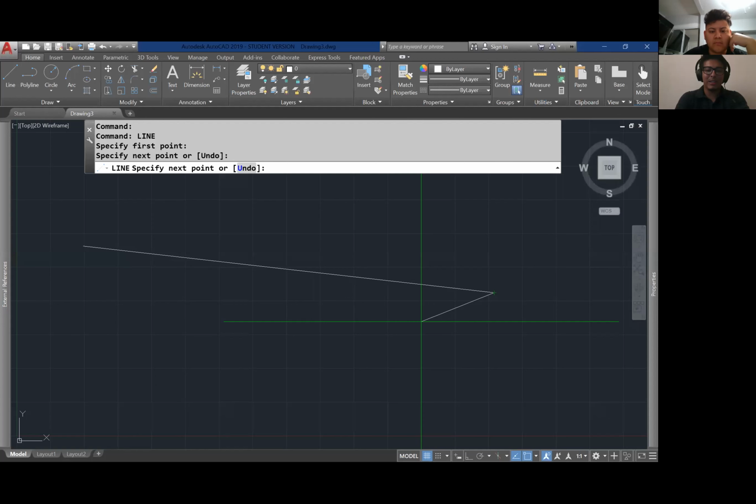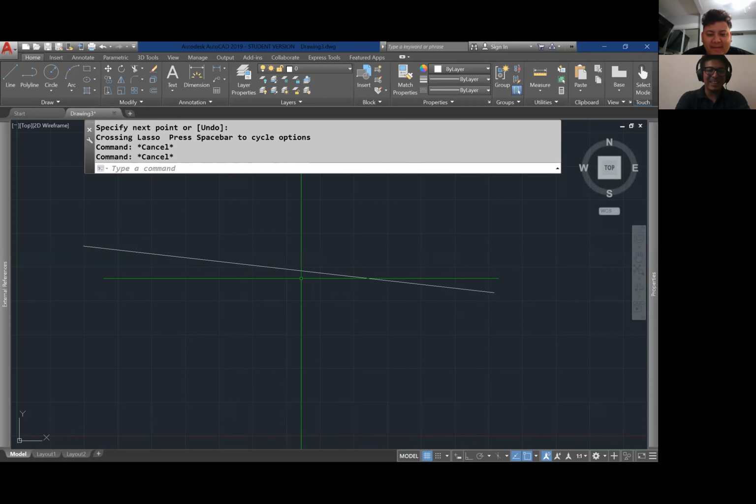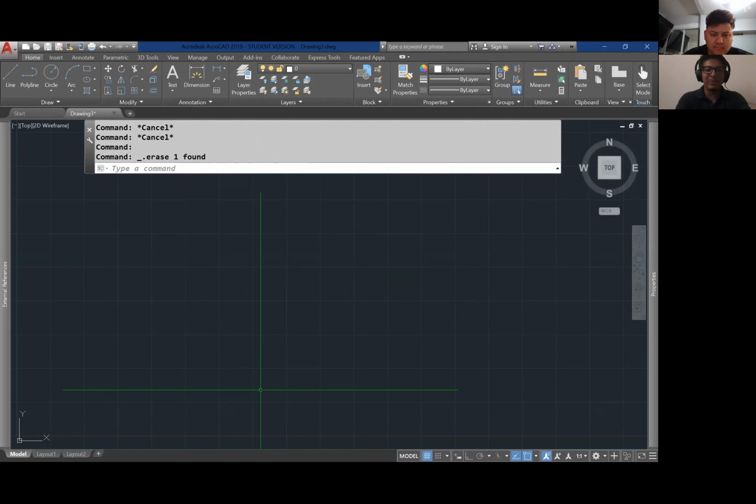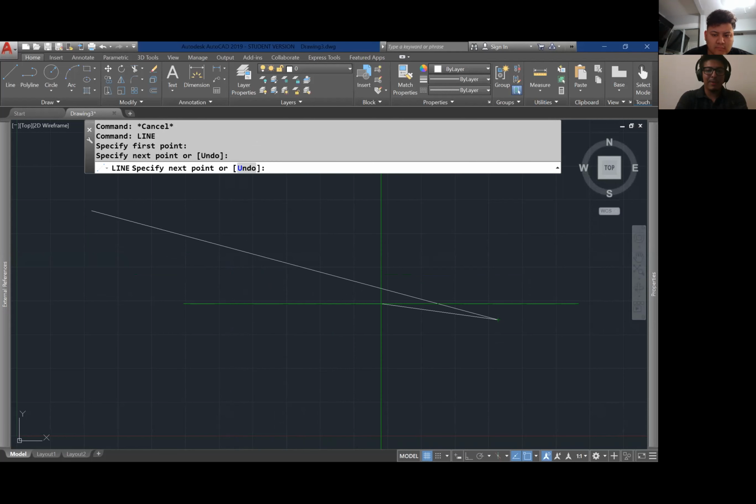It draws a line. Oh, yeah, the recording. And yeah, it draws a line. And then you can click on the line, hit delete on your keyboard, and everybody sees it. Or you can just draw that line again, type in line. Bam. Hit enter, hit escape.